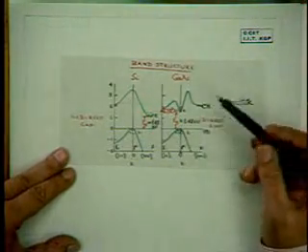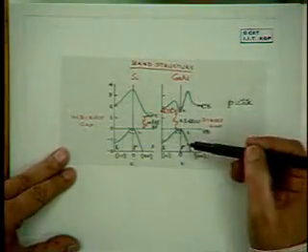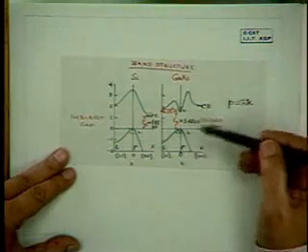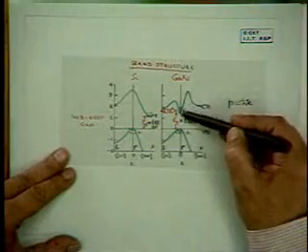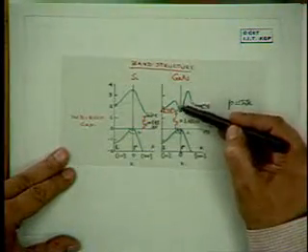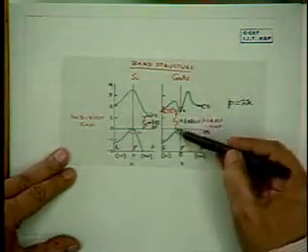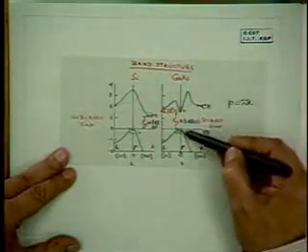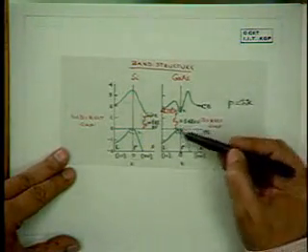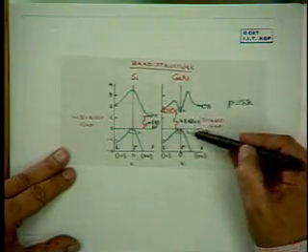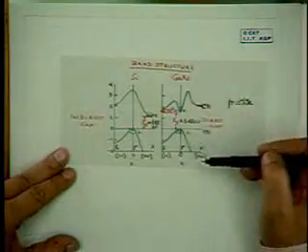So under thermal equilibrium, at normal temperature, 300 degrees K, we find that electrons are located in the lowest energy position of the conduction band, and holes are located at the highest of the valence band, or as we know that the hole energy increases downwards, so this is the lowest hole energy and this is the lowest electron energy.